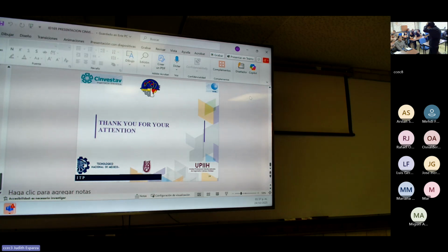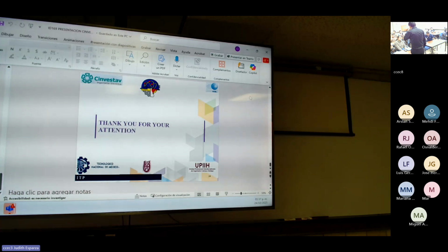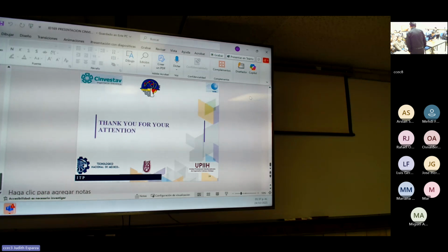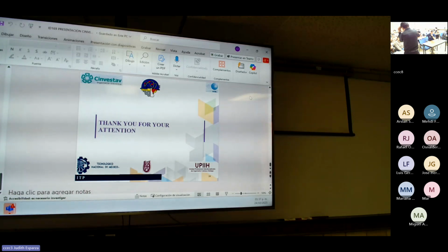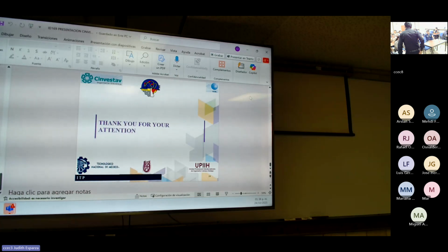Please. Some comment: the accelerometer has to be located in a position where you measure the first mode shape, because you're modeling the first mode shape of the tower. So you cannot put the accelerometer anywhere. Okay, and have you performed some finite element analysis or experimental analysis with the complete structure, tower, boundary conditions, and the wind turbine? Because the dynamics is more complex when you consider the different elements.